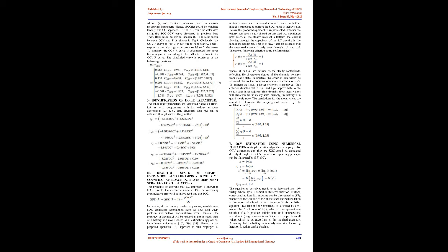1. Identification of SOC-OCV curve. The hybrid pulse power characterization, HPPC, test with 1-hour interval and 5% SOC each time was carried out. [27] Due to the employment of accurate measuring equipment, the SOC could be calculated accurately based on measured data, and OCV could also be accurately measured after a long rest of the battery. The SOC-OCV relationship curve fitted by a 5-order polynomial is shown in Fig. 2.